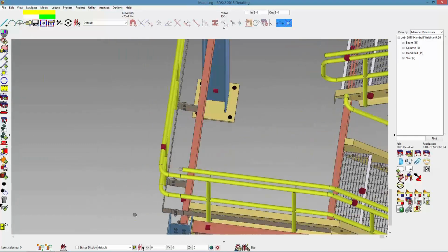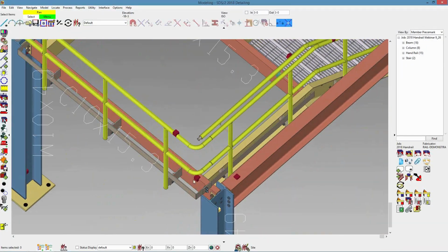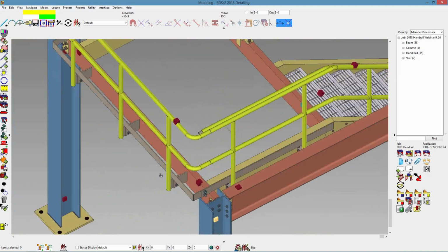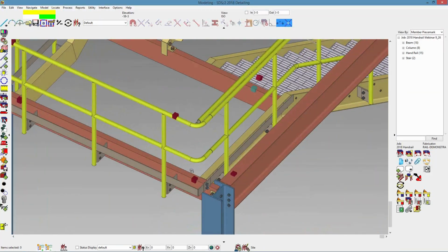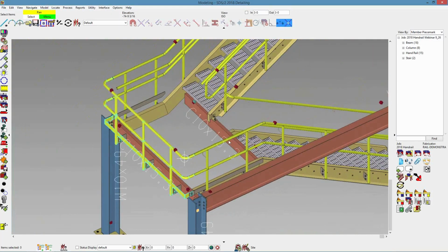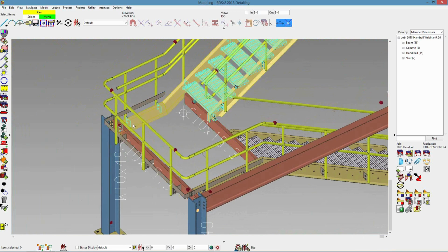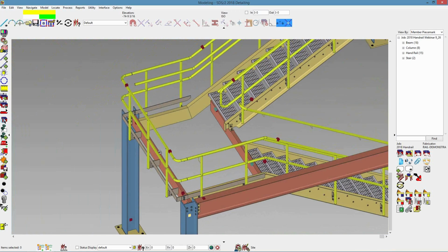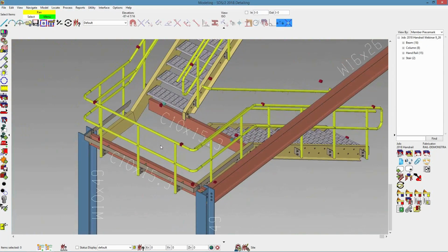And so it kept it at my offset. I had these offset already at 3.5 inches, and it knew to keep that offset out there. It did the math and created that shear tab to make sure I get those returns in there as well.